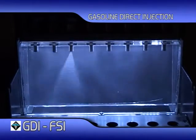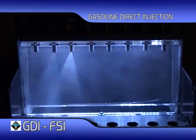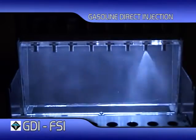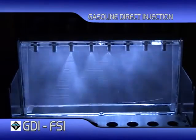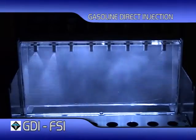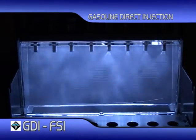The difference in the spray patterns and failure in the electronic operation would mean many of these are not acceptable to be returned to the engine. Even if the flow rates were correct, unless the sprays and operation are correct, they cannot be used.